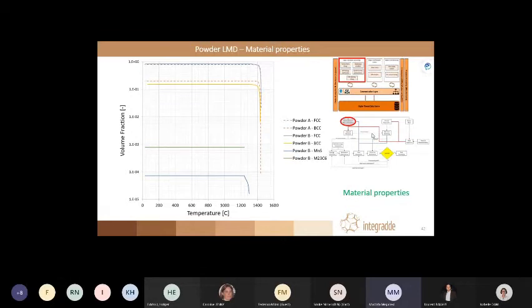we look at how the material is going to provide. So when I have a melt pool, the melt pool cools down at a certain speed, so the cooling rate. The cooling rate is, from the metallurgical point of view, very important because it dictates material properties. Here we use the information from that very small scale model to perform thermodynamic calculations to assess feedstocks.